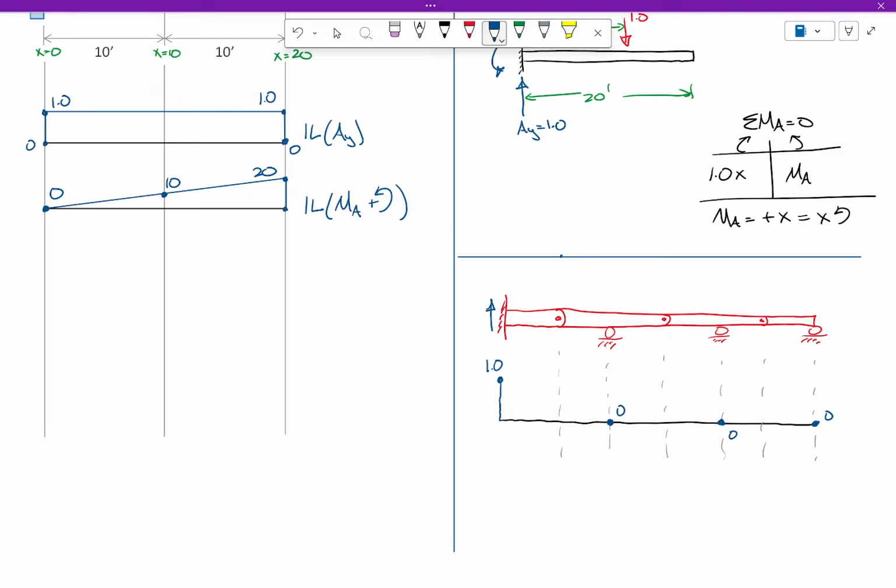Is that a fair statement? So what would the influence line for that vertical reaction look like? Okay, I've got to pick this point up, so I'm picking this up. This is flat. Flat. And then it seesaws the rest of the span.